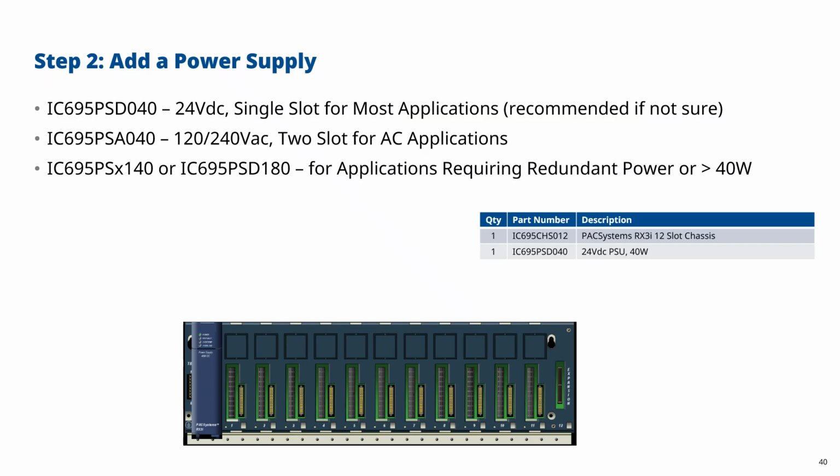So you could have 2 PSD140s, they're your multi-purpose power supplies, and they support N+1 redundancy, and they're suitable for use if you need more power or if you need redundancy or both. And these days we've also got the PSD180, the AC power supply, very rarely used, but again, quite straightforward. You end up with 2 part numbers now for your chassis and power supply.